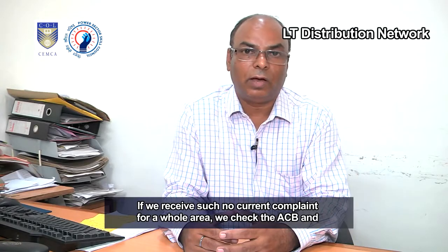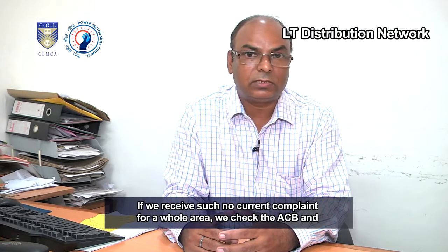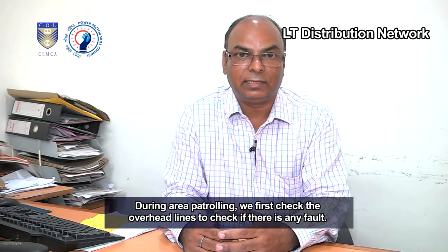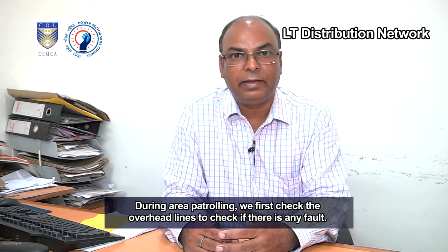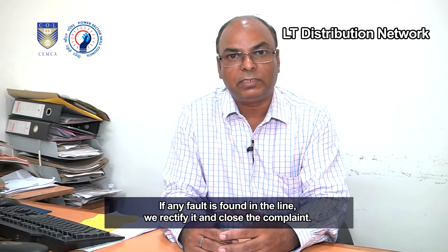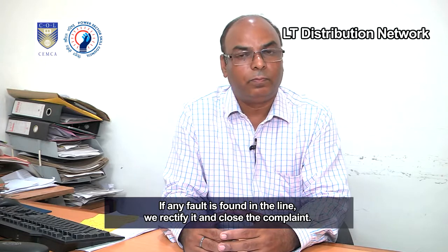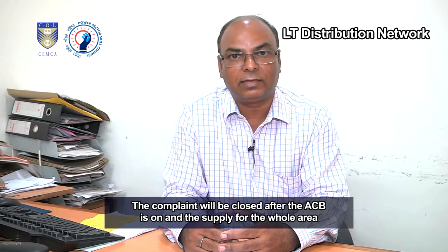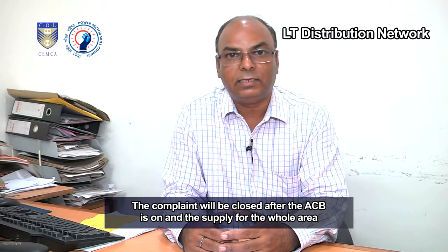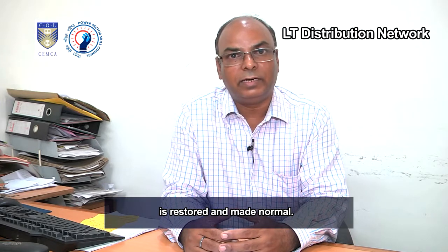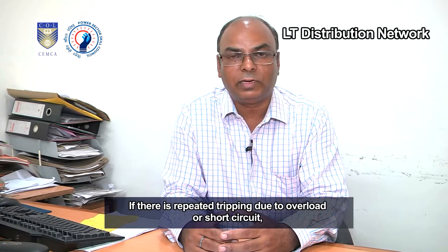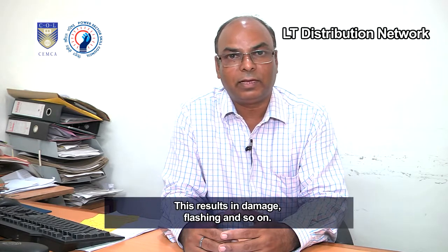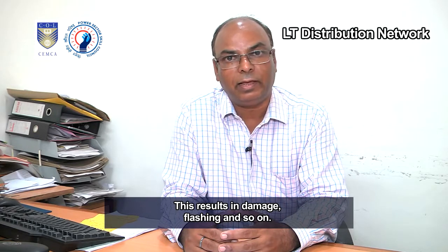If we receive such a no-current complaint for a whole area, we check the ACB and then do area patrolling. During area patrolling, we first check the overhead lines to see if there is any fault. If any fault is found in the line, we rectify it and close the complaint. The complaint will be closed after the ACB is on and the supply for the whole area is restored and made normal. If there is repeated tripping due to overload or short circuit, the ACB functioning becomes weak. This results in damage, flashing, and so on.